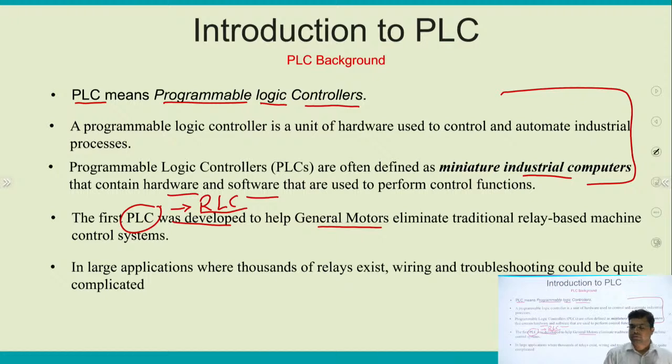The main disadvantage of using a relay logic controller is that a very large number of wires are used, and if we want to change any program or function, we have to redo the wiring. Another disadvantage is that if there is any fault in the system, it is very difficult to find where the fault is, and very time consuming. These are some disadvantages of the RLC system.